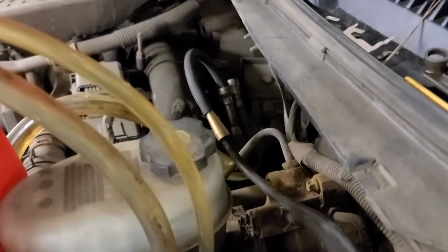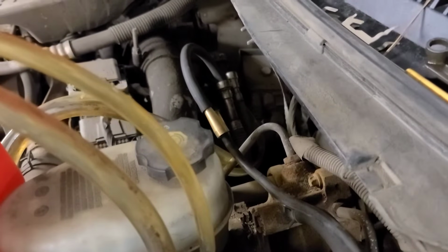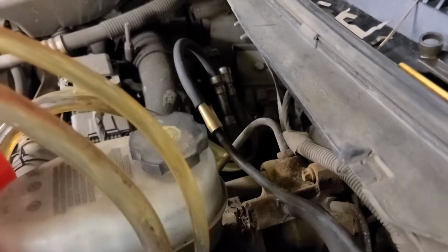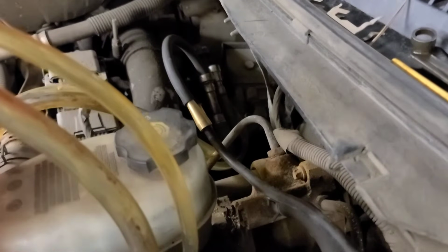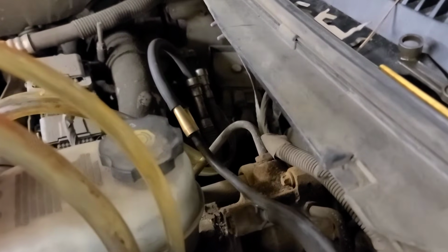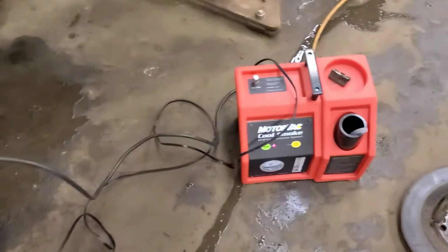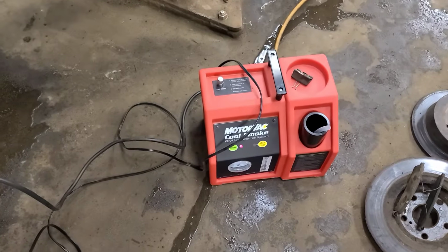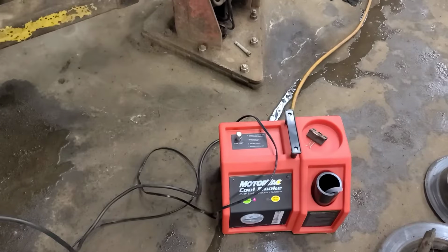So I did a visual inspection as best I could from underneath with my old borescope, and I can't see anything really bad with the top of the fuel pump, or fuel sender I should say. So I've blown fuel out of the line back to the tank with compressed air gently, so that line should now be empty, and I'm putting smoke into that line with my Motivac smoke machine, and we're going to raise it up now and see if we can see any smoke coming out anywhere.